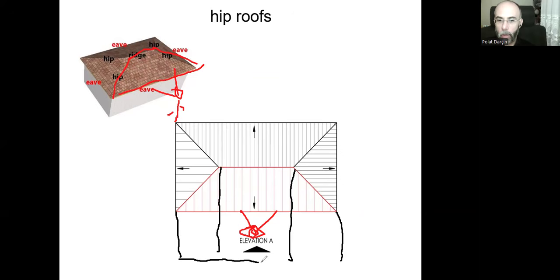First, I need to draw the eave at the same level. It has a thickness. And then I need to do the slope. Let's imagine the slope is 30 percent this time. This is how we do that. The first point, I need to draw 100 units, find the second point, and go upwards for 30 units this time, 30 millimeters, let's say, and find the third point and connect the first and the third points. There we go. That's the inclination.